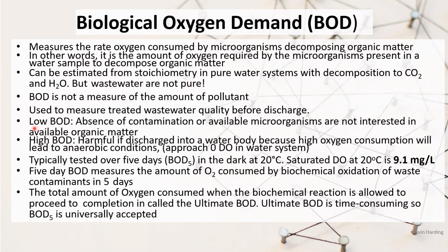If we have a low BOD, so what it is used to measure treated wastewater before we discharge it. If we have a low BOD, it means there's no contamination or available microorganisms can't use the available organic matter. If there is a high biological oxygen demand, it can be harmful when placed in the water body because of the high oxygen consumption rate, because these microorganisms are consuming all of these